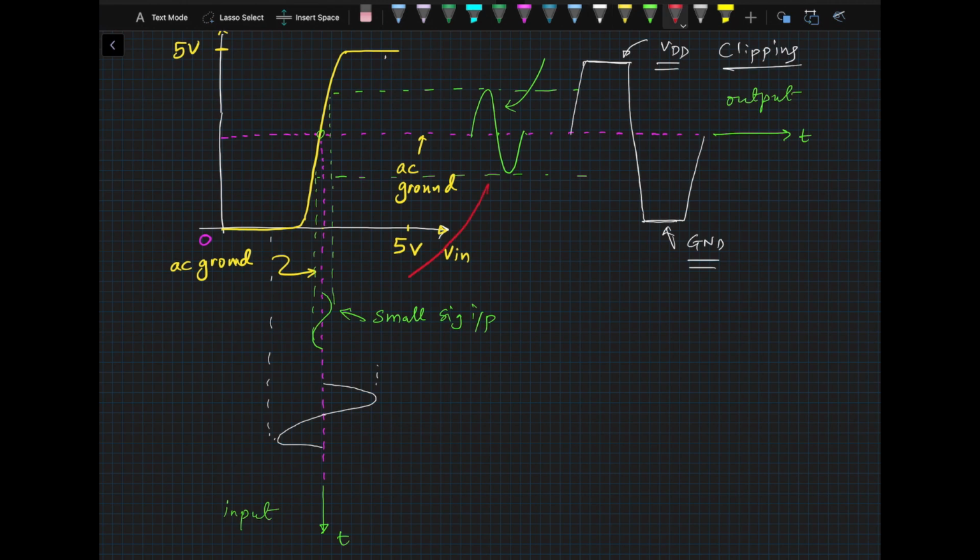Okay, let me show it in the red here. This is what we are trying to do. So we do a DC analysis. The DC analysis helps us find the operating point of the circuit, which is the red here in this case. What that means is I have applied a DC input voltage at this point, and my output DC voltage would be this much, whatever that voltage is. That would be the DC analysis. Once I do the DC analysis, I will know how much current is going to flow through the device and what the characteristics of our device are.